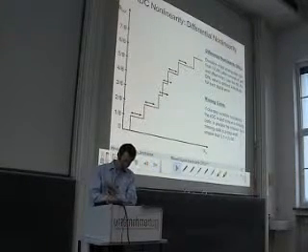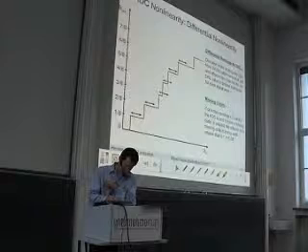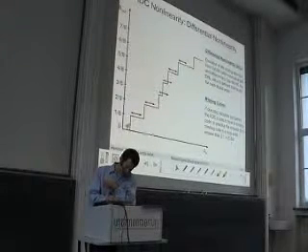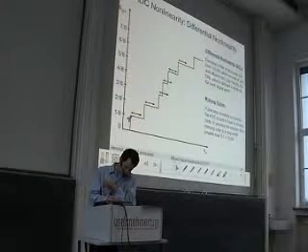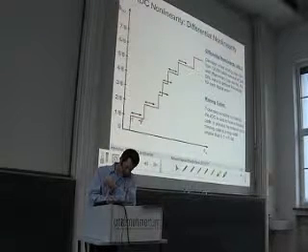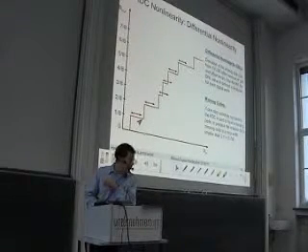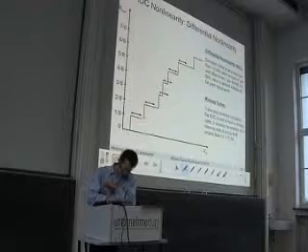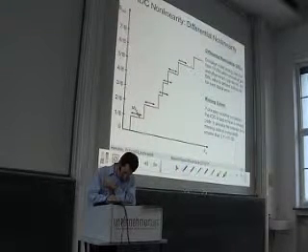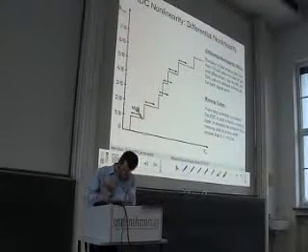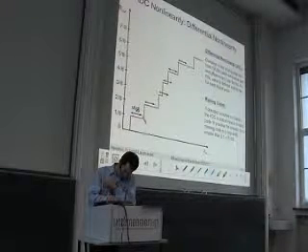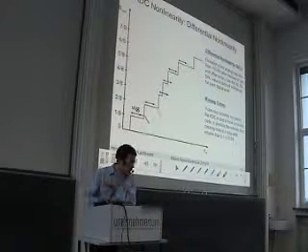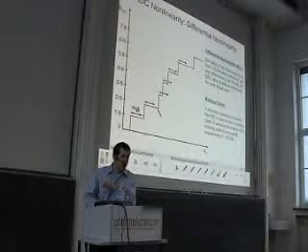So we can look here and say, okay, if we look at this step width, then this is larger than 1 VLSB, so this is VLSB. Here it is a little bit too large, and the difference is what we call the differential non-linearity.